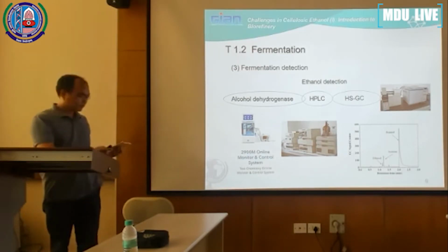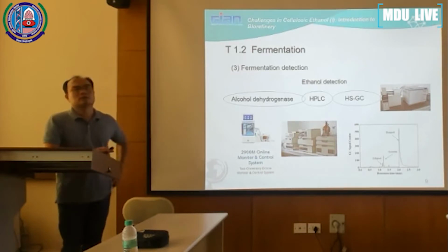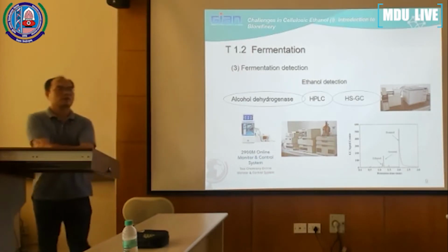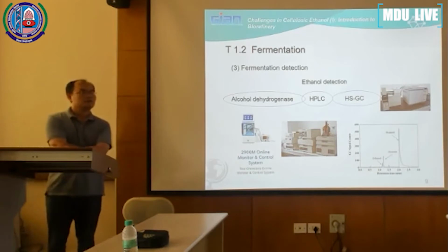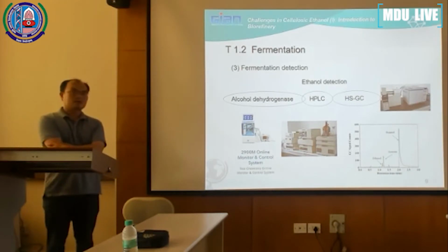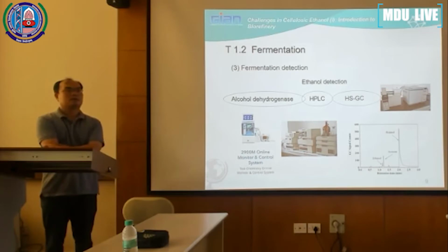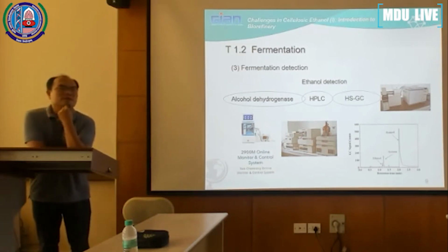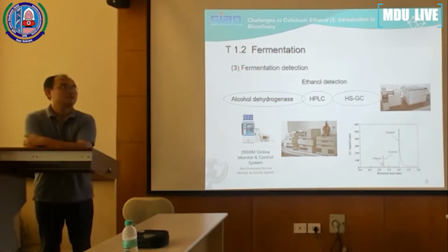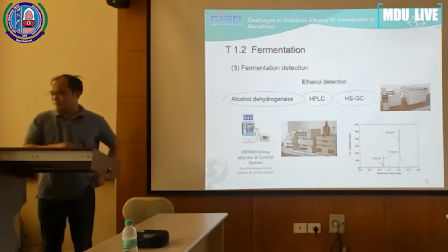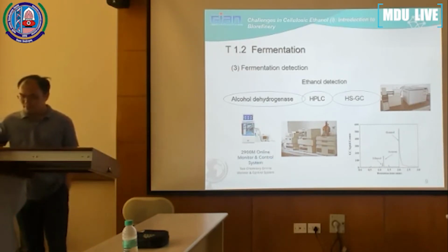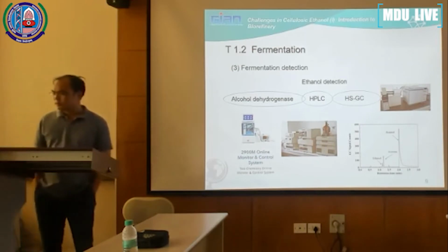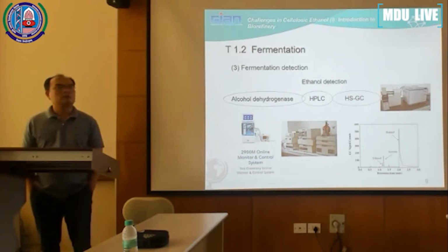In your sample, the amount of ethanol might not be that much to be fetched to GC. So this headspace concentrates the ethanol, so that you lose the water and have more of it. It's much more sensitive than simple GC. It's an attachment which further increases the concentration of your ethanol, otherwise you would have to load more volume in the GC.